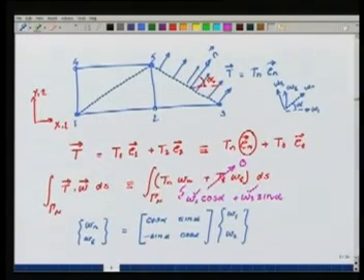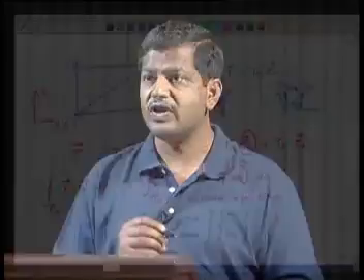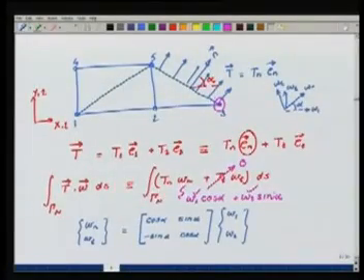So what will happen to the nodal equations? I will write essentially Tn into W into cos alpha integrated against the phi corresponding to this one, which will give me the first load term. Okay, let me do it. Let's say corresponding to node 3, what will I get as my load contribution corresponding to phi 3?